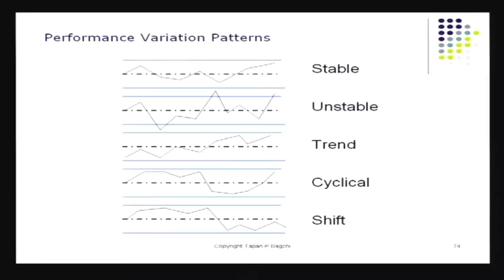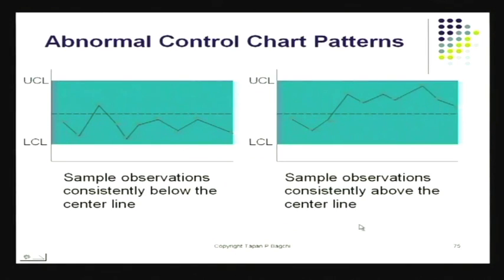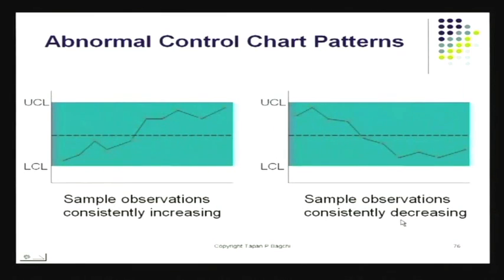Now if you watch the height of the chair at different hours in this studio, you'll find that the height is changing like this. It is going up and down like this. And that is exactly a shift in the average. That's the lowest pattern. This is something we'd like to see. So the same kind of abnormal behavior is there. You see the chart going from one side of the midpoint to the other side of the midpoint. This is also a signal that something is happening with the process.